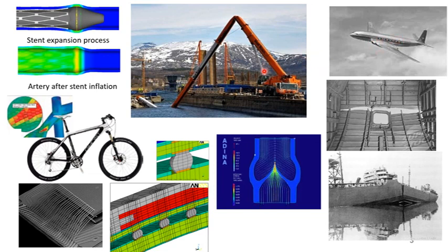This is showing an electrical component, the connection. Due to current flow or signal, the connection experiences heating, and the heating is cyclic. Now, if you remember, we discussed thermal stresses in chapter 2. Thermal stresses from changing temperature, high and low, are called cyclic loading, and the failure in the IC connections is due to fatigue, which is due to the cyclic loading of changing temperature.